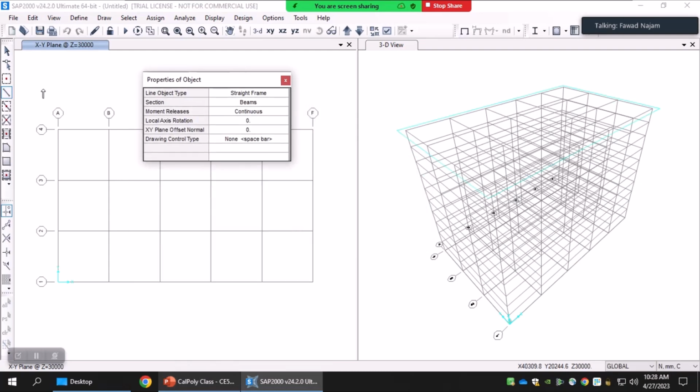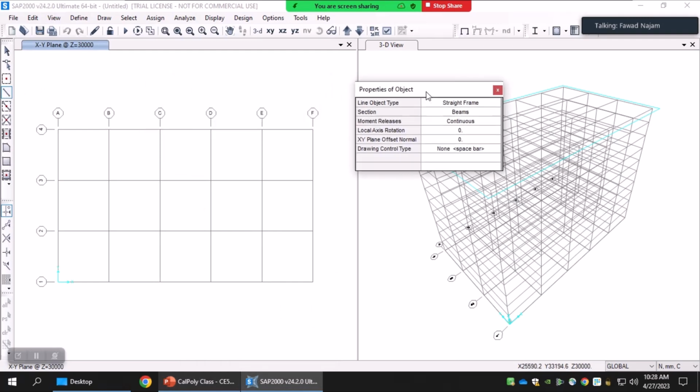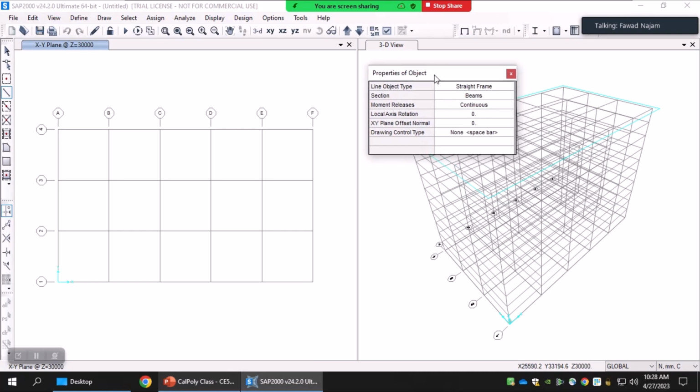So when I click on this particular button, this additional box appears, which I can just move anywhere on the screen. And in that box, I have to essentially select one thing which is most important, and you can see others also. This is the cross section. So this will show the list of all cross sections which we have defined while defining cross sections for frame elements.